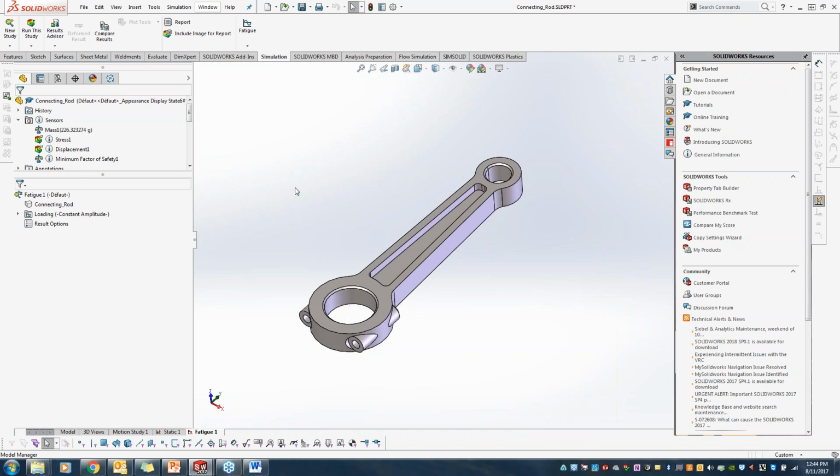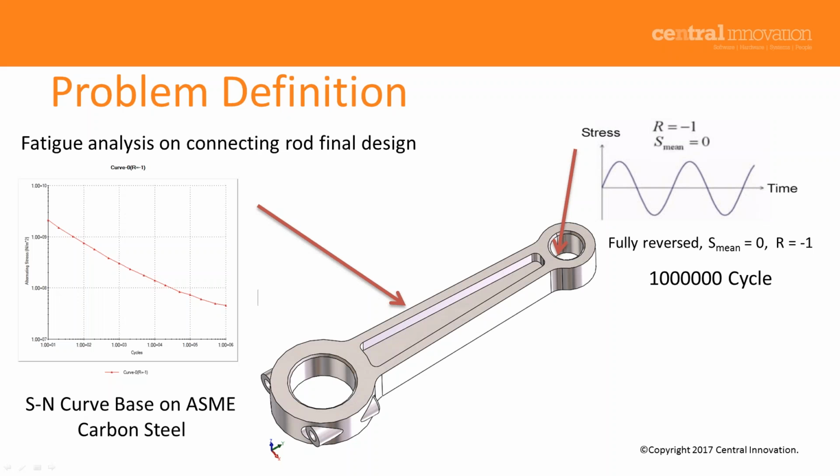Now, it's more than important to always remember, for fatigue studies, if I bring my slide back here, there is a relation between how much stress a component can tolerate and the number of cycles. The highest stress can be tolerated for 1 cycle, and if you're repeating, the value of tolerable stress is reducing. And that's why fatigue is starting. So this is called the SN curve.